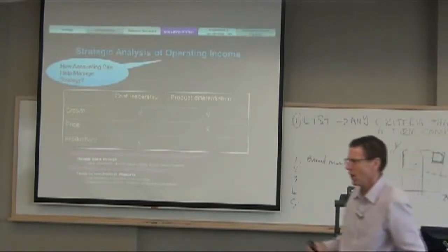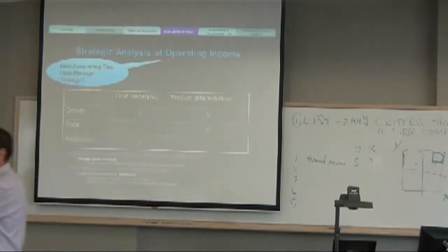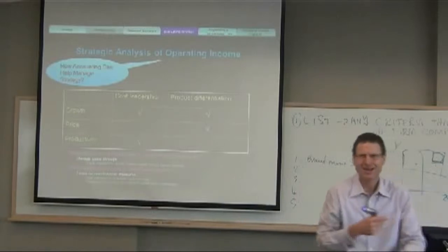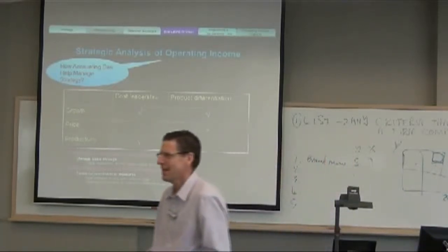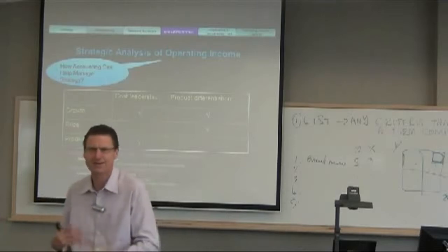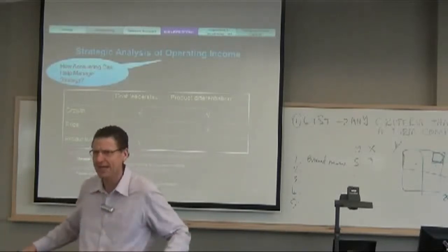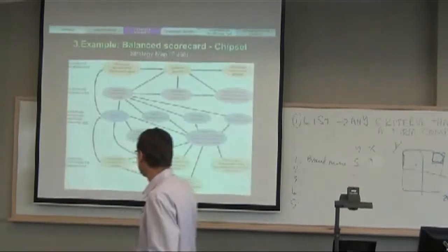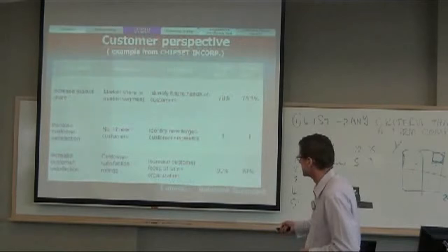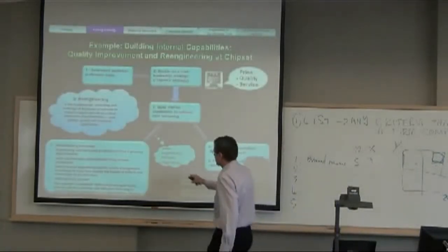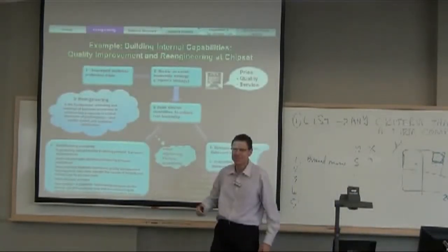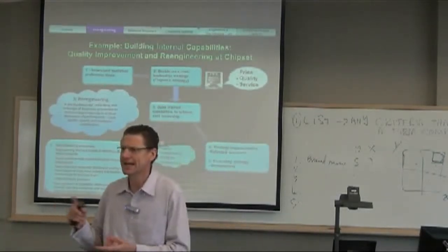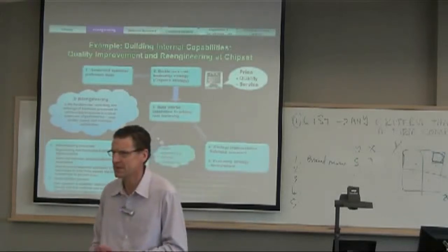I'm thinking, why is that person moving it 50 metres from here all the way up to the other end of the line? That doesn't make sense. That moving is non-value added activity. You cut all that out when you're focusing on improving productivity. You cut all that out when you're focusing on this thing here, this little thing called process engineering. Process engineering is all about streamlining processes, cutting out all the moving times, the waiting times.